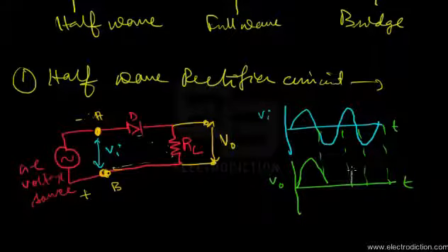So we'll have again a similar output voltage that varies in direct proportion with this half cycle over here, I mean with the third half cycle, and we have an exact replica of the third half cycle at this point. And similarly at the fourth half cycle, which is the same as the second one, we'll have no output voltage. So that being said, this is pretty much the output voltage that we obtain for a half-wave rectifier circuit.